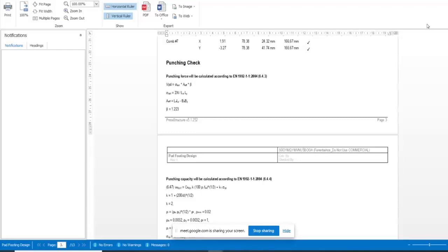So deepening the sections of your concrete element could prevent that. And also making the thickness around the column thicker could help against that. So that's good.